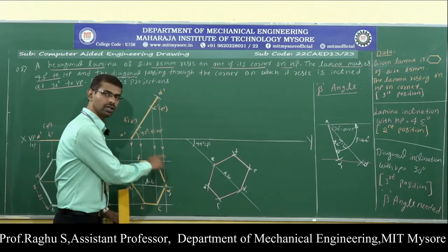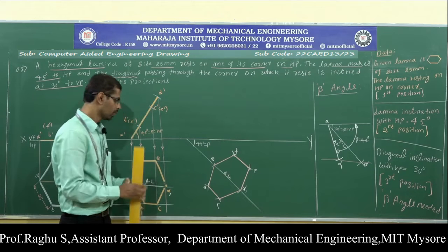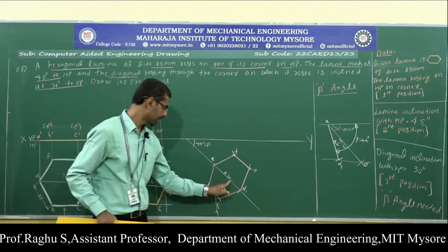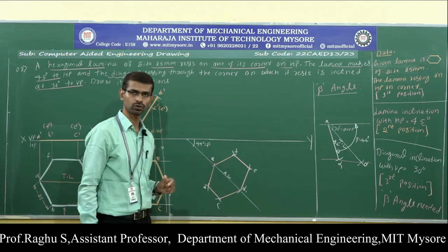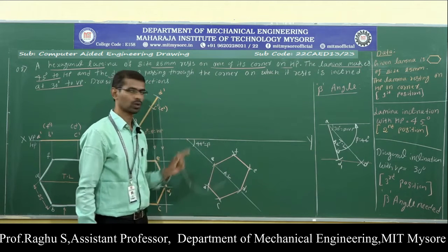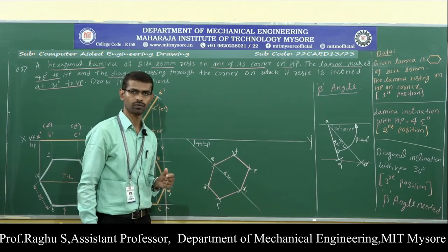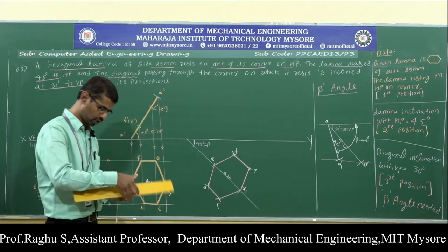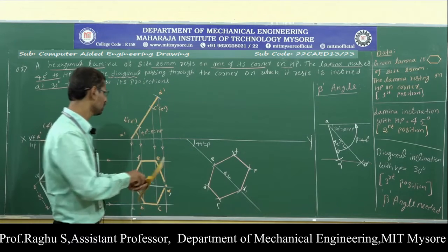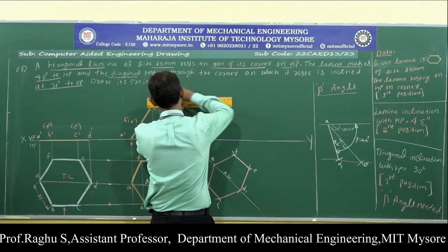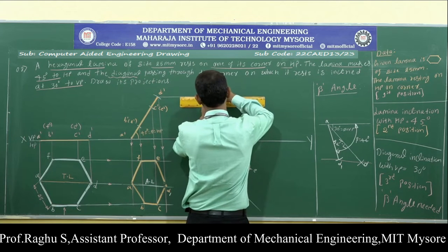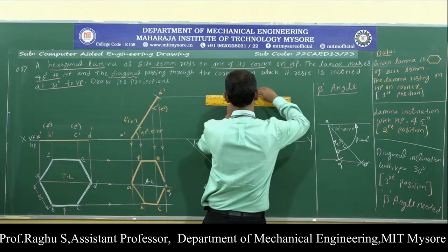Okay, here I have redrawn this diagram by placing the diagonal AD1 on the beta angle line. Next, draw the horizontal projections and vertical upward projections to get the final view. First, I am drawing the horizontal projections from the second position front view using thin lines.